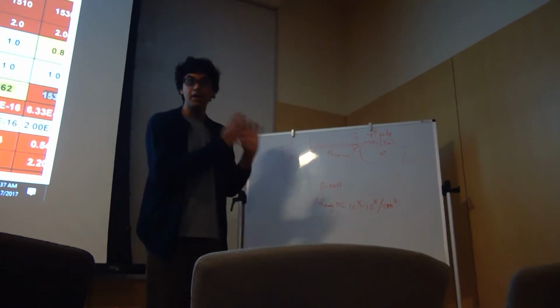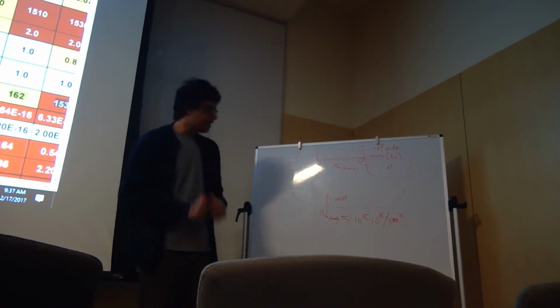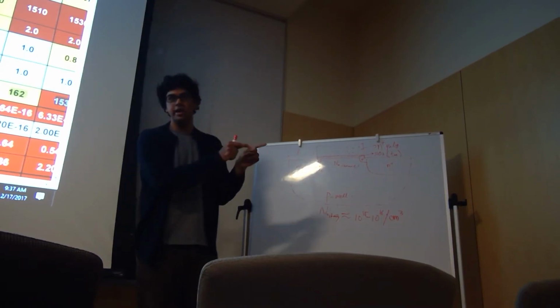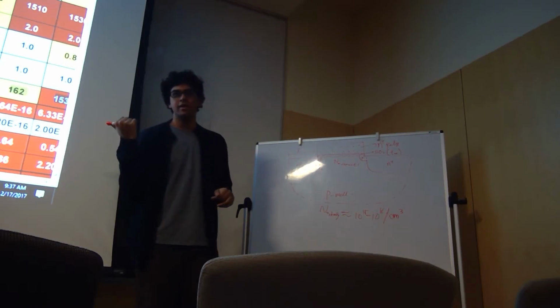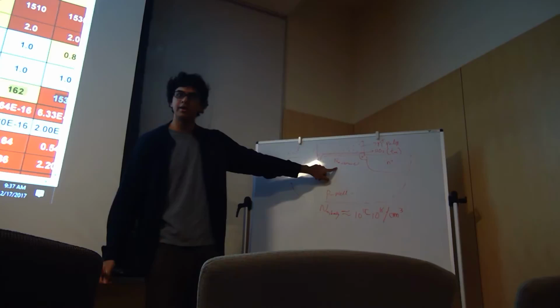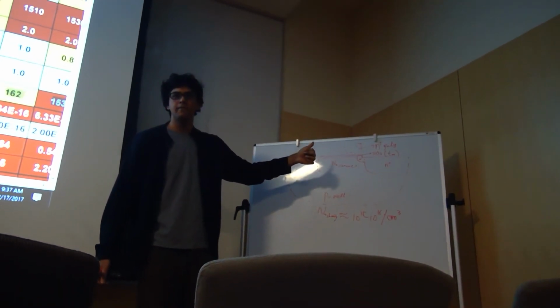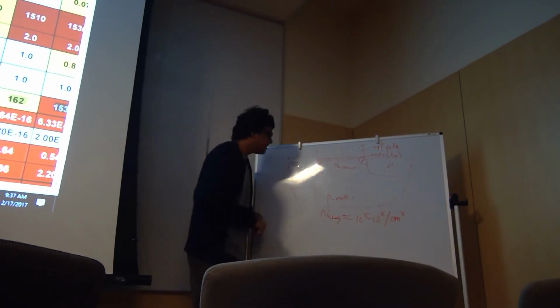No. When you make NMOS, your substrate has to be P-type. Even though your substrate is P-type, in order to get the required threshold voltage you need to make the doping a particular level, which you're going to calculate. So you need to make an implantation here and adjust your doping so that you get that threshold voltage. And that has to be P-type doping? Yeah, because NMOS is P-type. Right. And PMOS is N-type. Yeah.